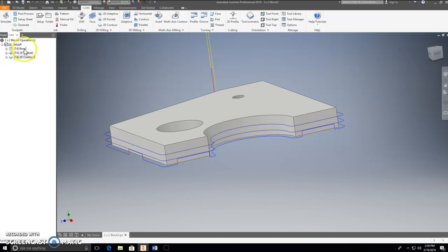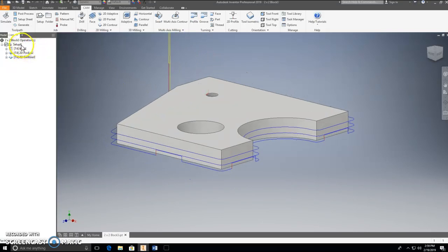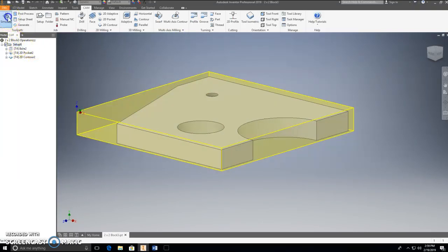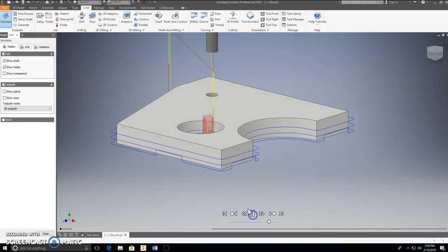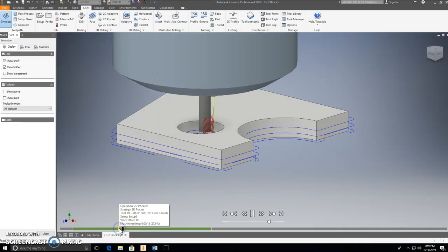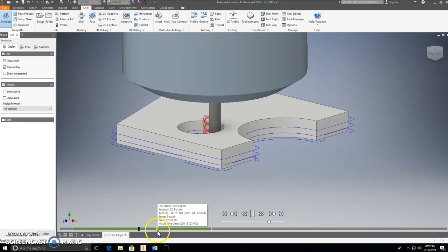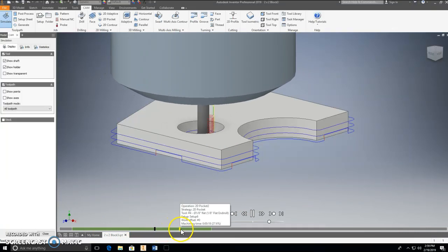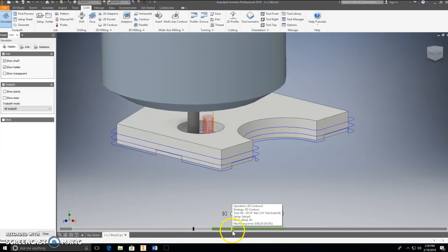That's it. Everything has been updated here. So now we're ready to actually export this. But possibly before we export it, let's go ahead and look through our simulation one more time just to make sure we got it. Drills that hole, comes over here to this next portion, goes down to that depth, spirals around, down to the bottom depth, spirals around, does all that.